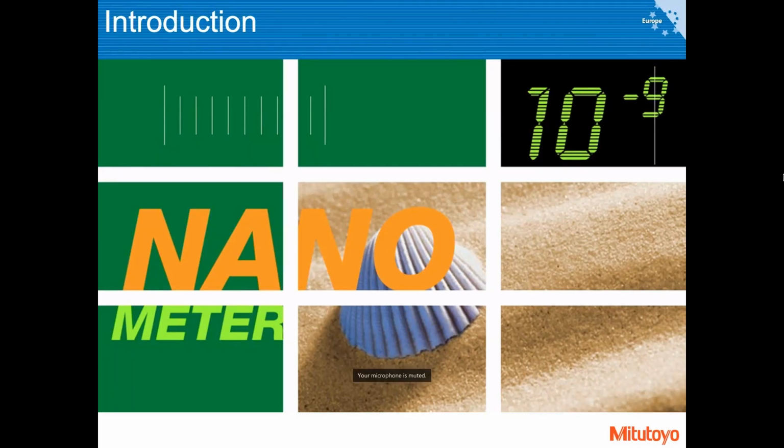So this is the reason why things related with either high pressures or low pressures typically have a higher need for smoothness. Also, the surface roughness can initiate fracture of your component.